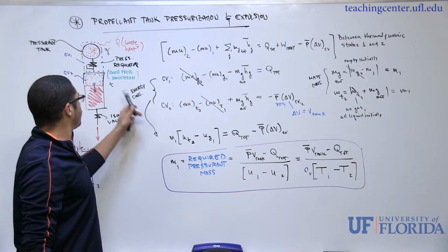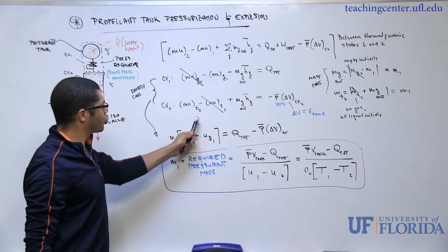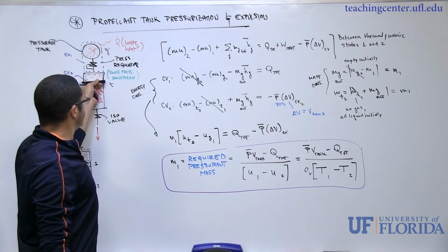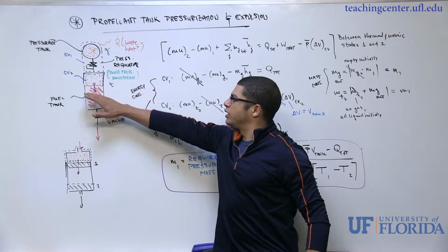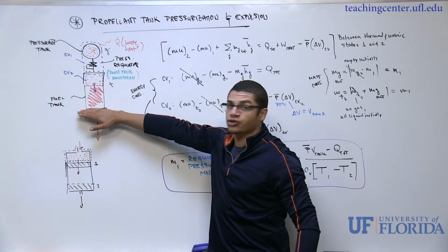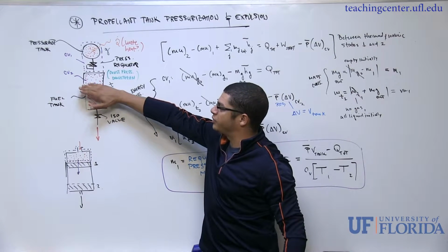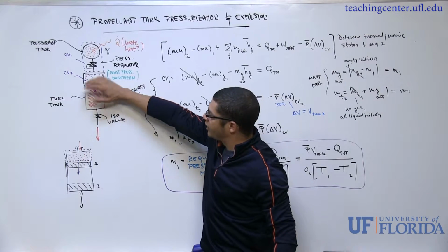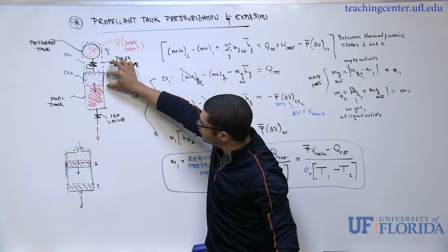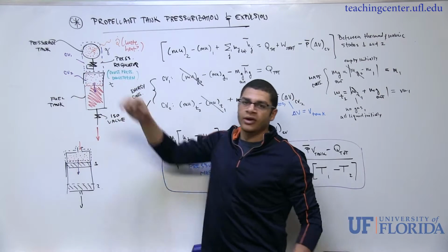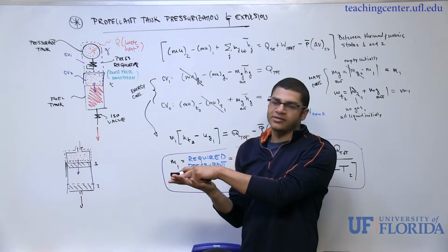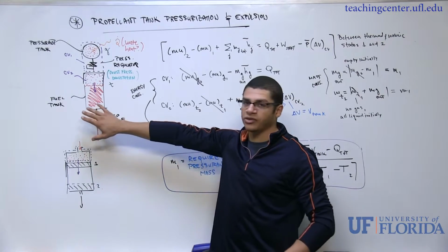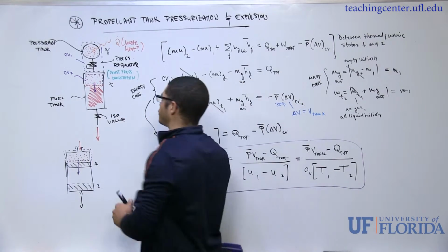Now as far as the second control volume, we have the internal energy of the gas at state 2. State 2 would be when this control volume over here is fully flush with the entire fuel tank volume. Initially, we'll assume that this CV is just kind of a line or just a plane, so there's no mass inside of it, and eventually it expands all the way until it's hit the bottom of this tank. So that's going to have some implications on our initial and final conditions.